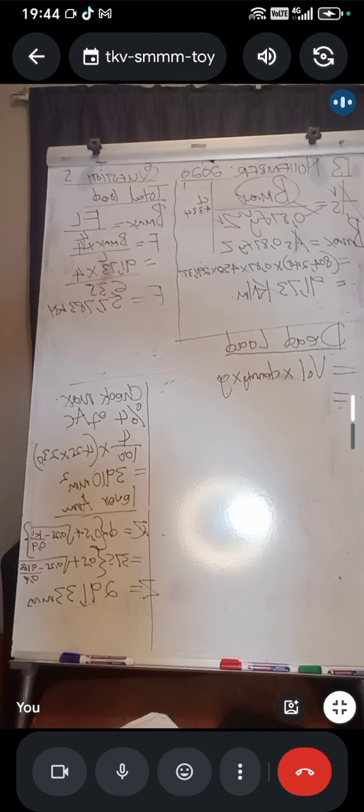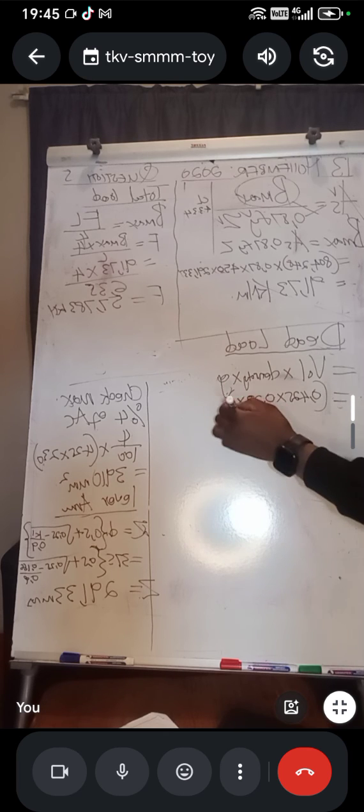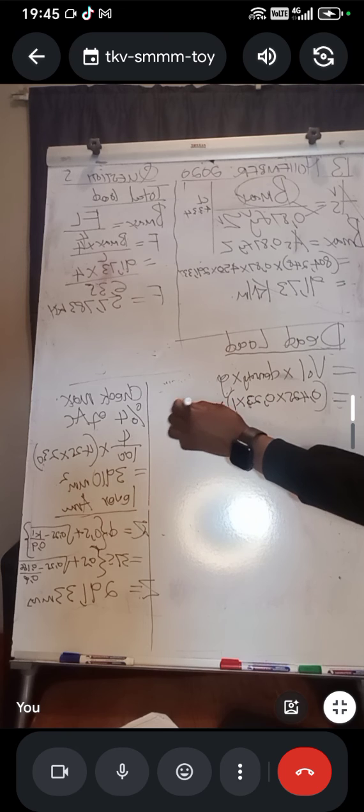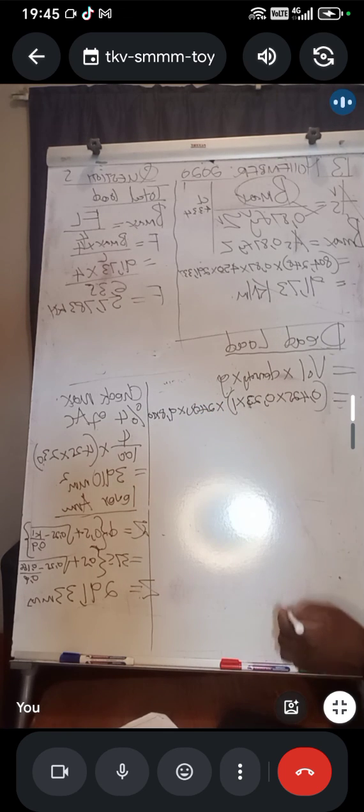A volume of the concrete, we take what, the width. The width, let's do that in meters. It was 425, ne? Yeah. 0.425 times what? 0.23, it was 230. You multiply it by 1 because it's per meter. It becomes a volume. Multiply by density. Multiply by 9.8 times 10 to the power negative 3, ne? Yes. What is the answer?